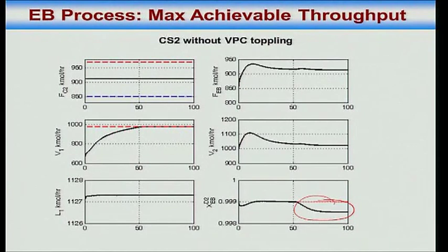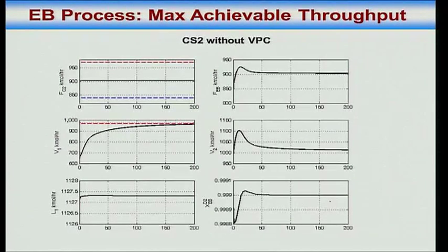Right? So what would an operator do? He will say, well, I am producing junky product. He will never exceed 840 kilomoles an hour. He knows that the moment I go to 850, the sensor keeps going here and there. If it goes there and I am having a cup of tea, I will be producing junk. Or I am not attentive enough, 15 hours later I will be producing junk. And then the next operator wouldn't know why that is happening, because the shift has changed.